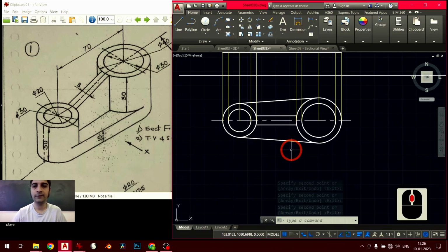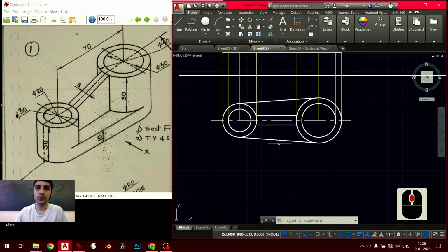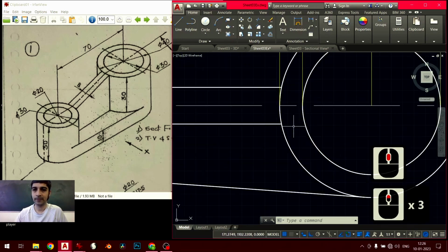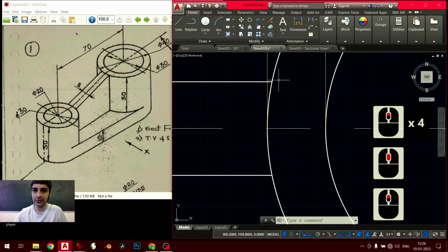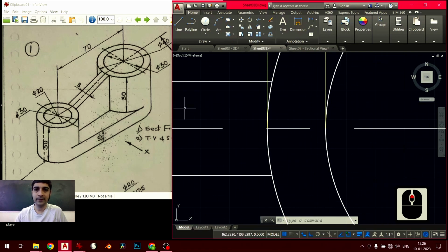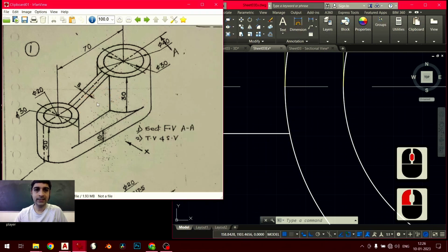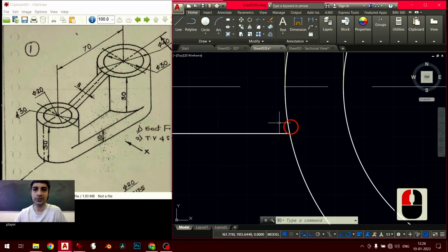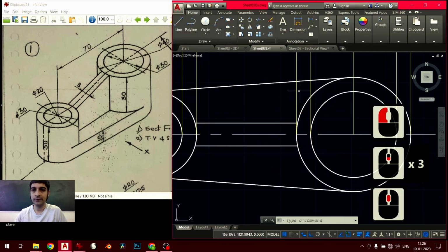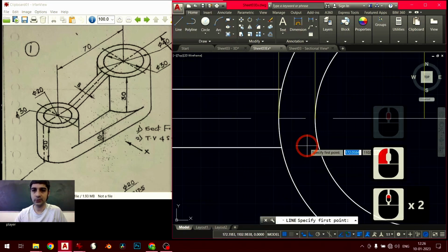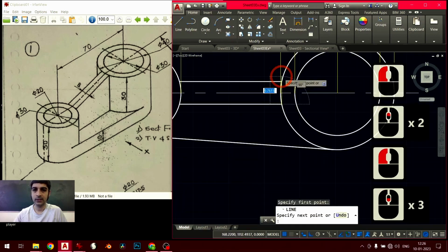But that's not the end of it. There are a few other things you need to project, and those are not very obvious unless you've gone through a body of work in orthographic projections. So for example, I'm going to project this edge, the edge where, on the other side, this plane of the rib meets this curved plane. I'm going to project that point up as well. And it's going to be very close to this other projector, so I'll have to be careful projecting this.